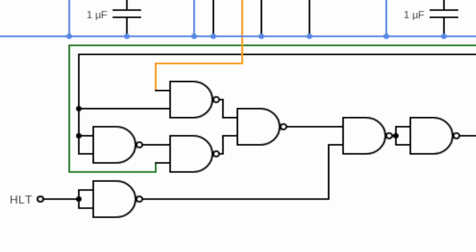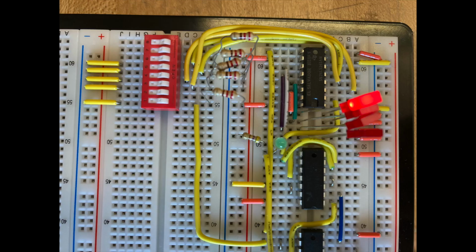The halt line at the very bottom, HLT, is used to cut the signals coming from the clocks at a certain point and is implemented in a later stage of this project. The clock signal from the NAND circuit is then fed into the program counter, which creates a 4-bit signal that increments after each clock pulse. Otherwise, it can also create a 4-bit signal according to its input lines, which are shown by the switches, if the load signal is low.